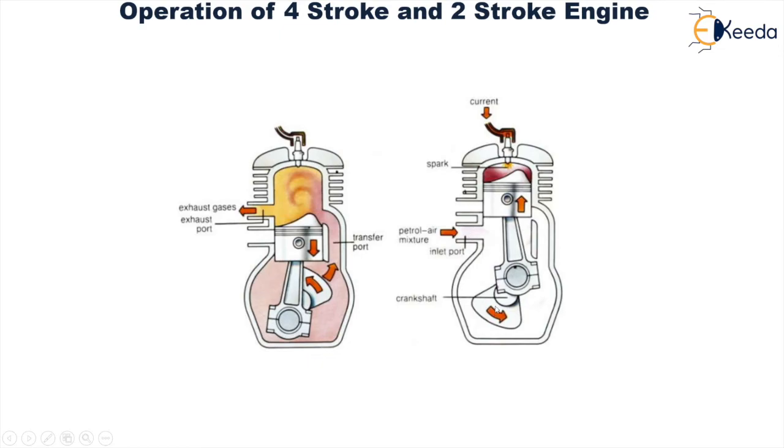So compression and intake take place simultaneously. Now when expansion takes place, when ignition of the fuel starts and its subsequent combustion goes on, the piston will move in a downward direction in the power stroke, and in doing so, as soon as it uncovers the exhaust port, whatever exhaust gases are formed will move out through this, which is shown over here. So power stroke and expansion, exhaust stroke, take place simultaneously over here: intake and compression, power and exhaust.